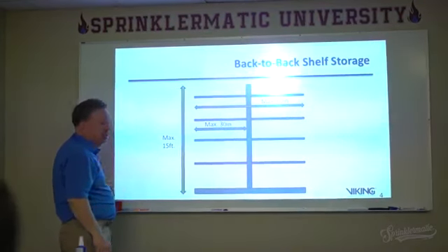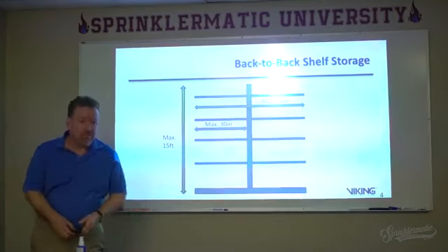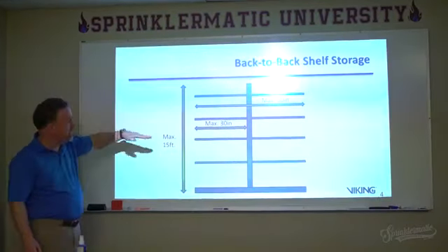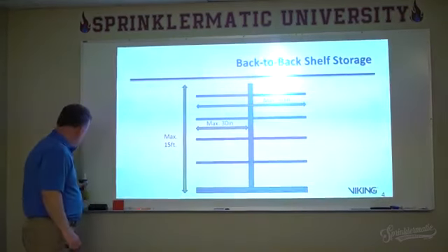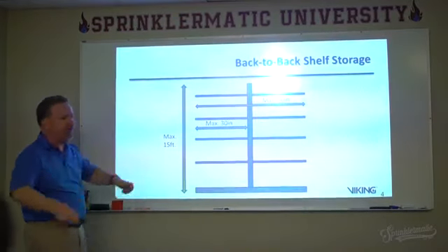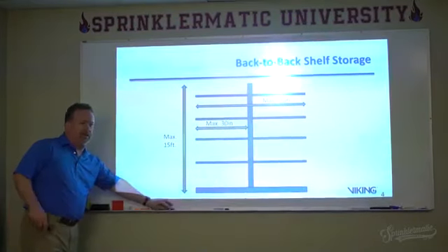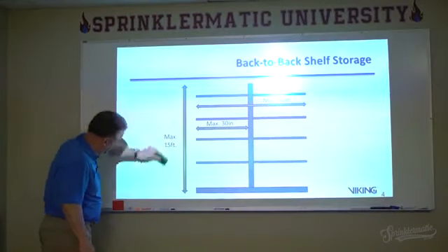Typically in a grocery store, you're going to have them what? Around, I don't know, 6 feet? 6 feet high, maybe 8 feet. So if you're under 12 feet, you're not even in the storage commodity. You're not even considering storage commodities, all right? Unless it's low piled storage and low density, which we'll get to in chapter 13 here momentarily.